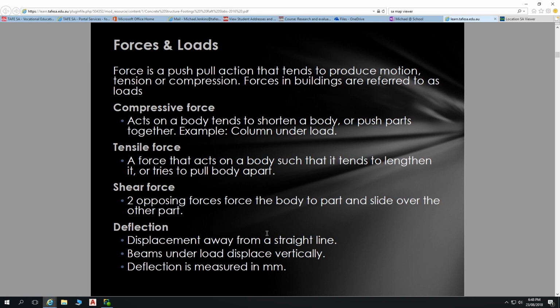Now, from a structural perspective, everything's going to deflect to a certain extent. Even concrete will deflect to a certain extent. With high-rise buildings, the amount of weight in a high-rise building needs to be catered for, as that building is going to compress slightly. We don't often think about high-rise buildings or concrete columns as being things that compress, but they do compress. Everything compresses slightly, and also everything deflects slightly. Now, what we want is for that deflection either to be hidden or to be non-perceptible.